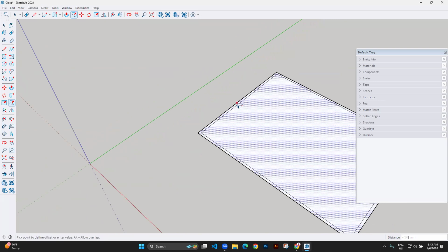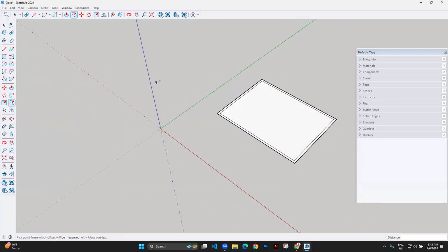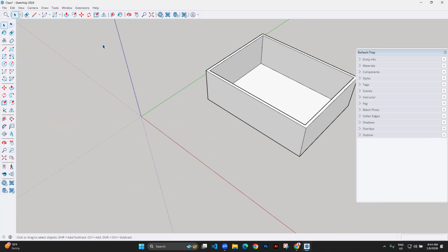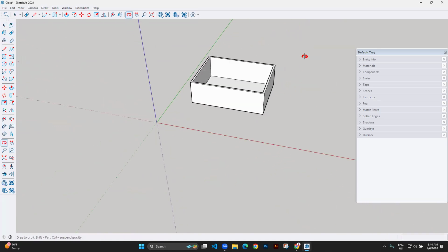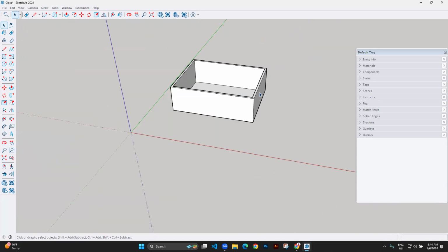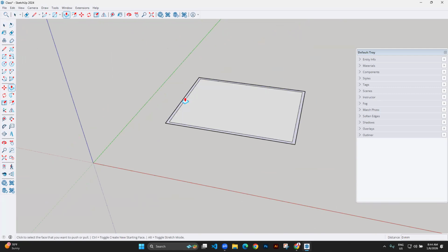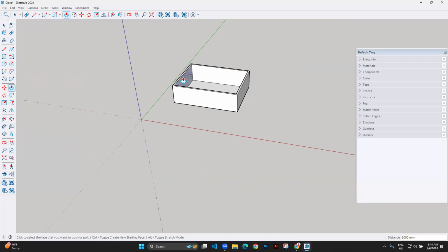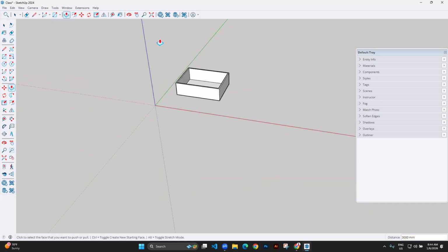So you type the distance. I could say the thickness of my wall is 230. Then I press enter. This will create two faces. There is this inner one, but this is not the wall, there's also this outer one. And you pull, like that. So just like that, we have a wall, which, as we push pull, we can give a height. So that can be a very great starting point.